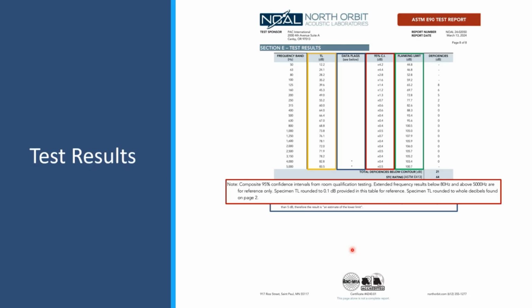There's the three different metrics. There's differences in whether they account for the absorption or the reverberation time in the rooms. Because if you have a really lively space with just a bunch of hard surfaces, very little acoustical absorption, your sound levels in that space will tend to be louder. Whereas if you have a bunch of soft surfaces that will absorb a lot of sound, your sound levels will tend to be lower. And so the ASTC and NNIC measurements try to normalize for that absorption or reverberation time and adjust it to a norm.